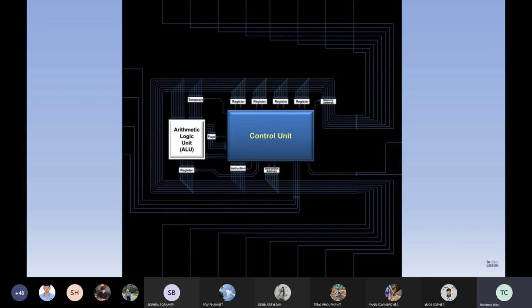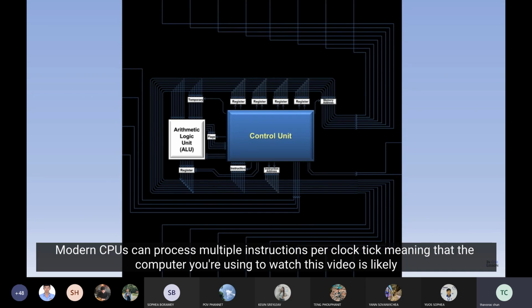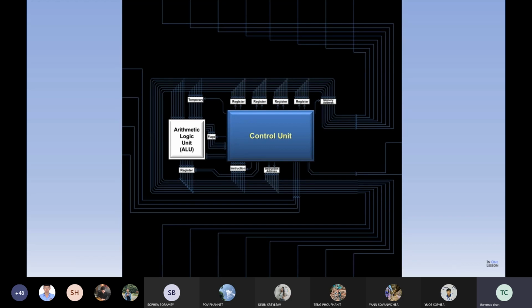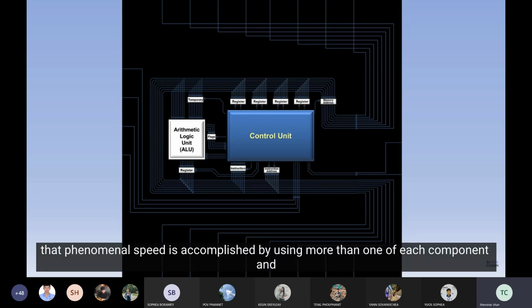out to the pins on the chip. On the right are the set RAM and enable RAM wires. On the top are the RAM address wires. On the bottom are the data wires that run to both RAM and the external devices. And on the left are the input-output control wires.